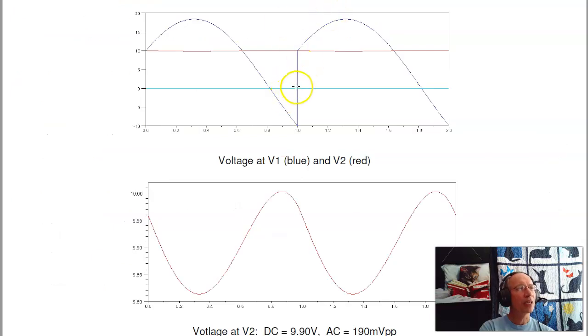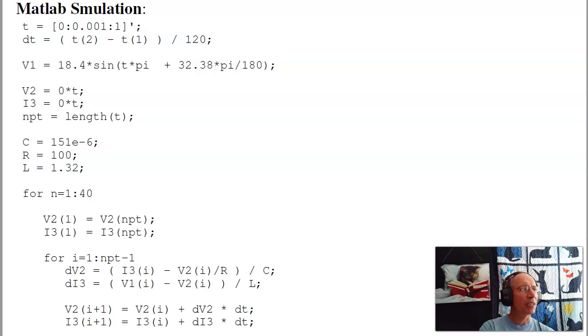And if I do that, again I get a very similar design. The voltage should be 10 volts on average, and the ripple should be about 500 millivolts. Again, our design's a little bit conservative, so I'm actually only getting about 0.2 volt ripple. But it's similar to what we wanted. And the corresponding MATLAB code, that's in the lecture notes if you want to see it.